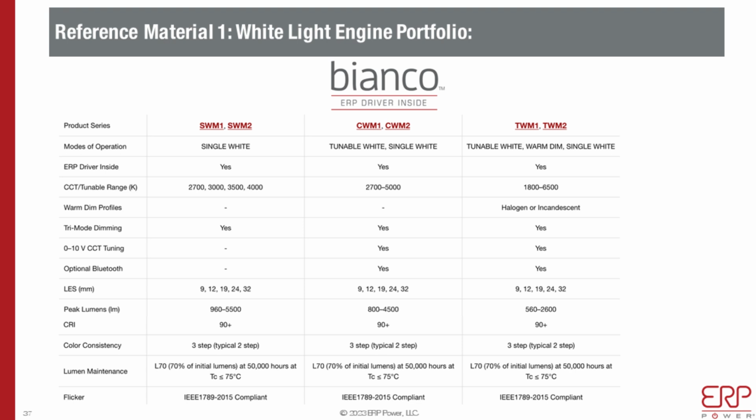So think about, if you just do a quick math on that, let's say you go 4,000 lumen with an LPW of, let's say, 120. You get about 33 watts. So 33 watts on a 120. But we are coming up with even more efficient SWMs. As I said, we're just about to introduce the 140 lumen per watt version. So that'll bring down 4,000 lumen to roughly about 27 watts.